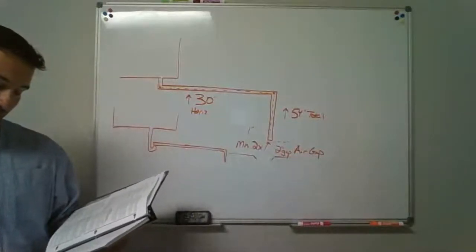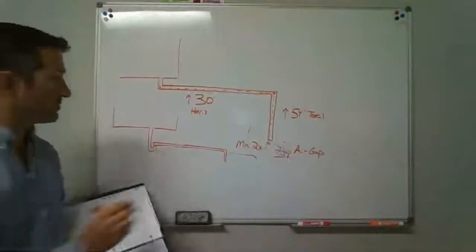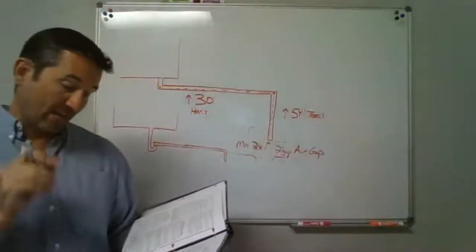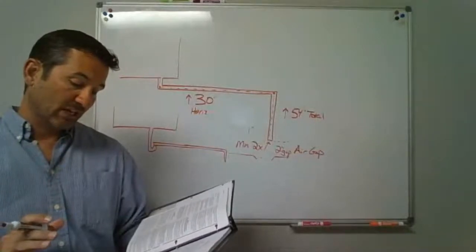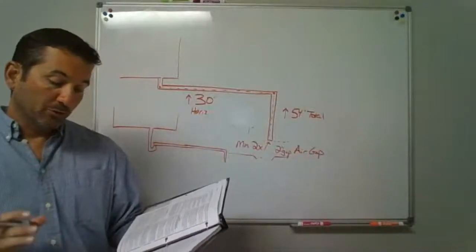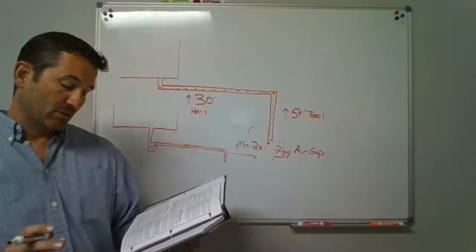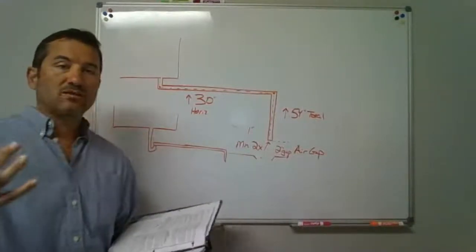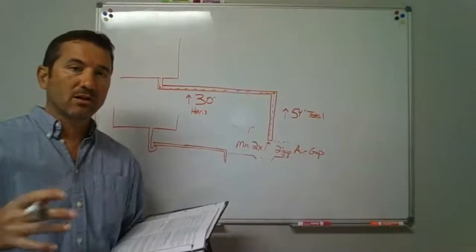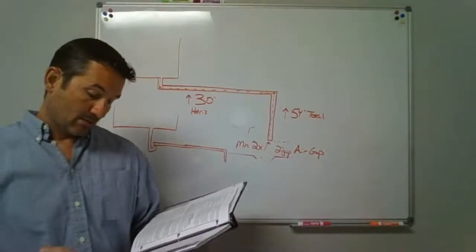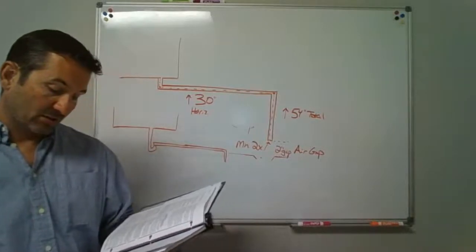Waste receptors. What's receiving it? This waste receptor right here. Let's give some rules for that. Every waste receptor shall be of an approved type. A removable strainer or basket shall cover the waste outlet of waste receptors. Being able to take that screen off, that strainer off, clean that thing out, okay? Waste receptors should not be installed in concealed spaces.